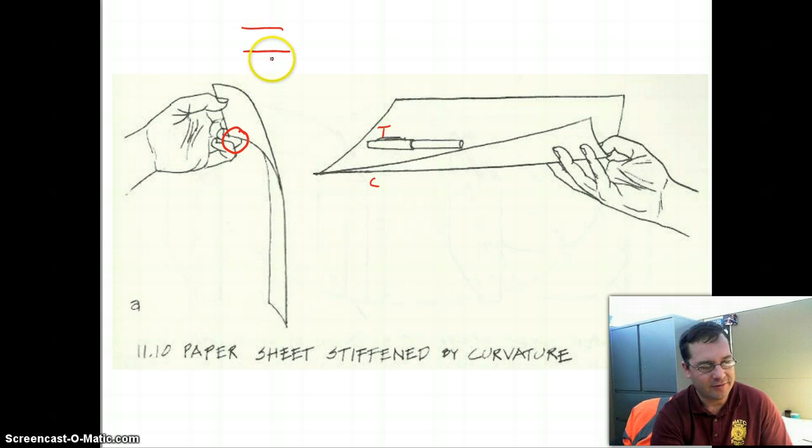And it's in a cantilever arrangement, so the bottom's under compression, the top's under tension, and in the middle here's the neutral axis. Well, remember that the extent to which the top is stretched and the bottom is compressed is proportionate to this distance from the neutral axis out to these, remember we call those things out at the far edges the extreme fibers.